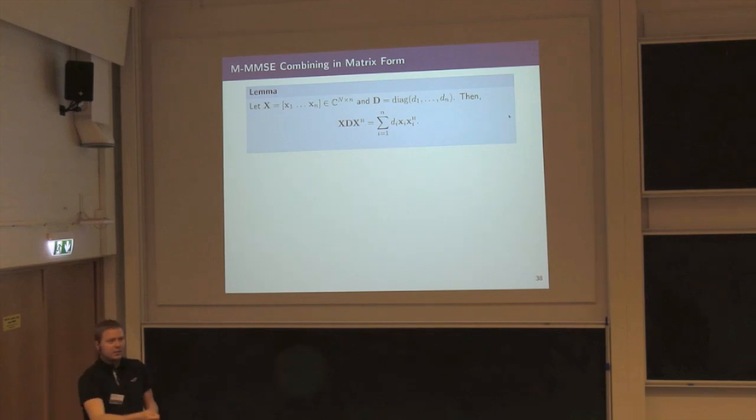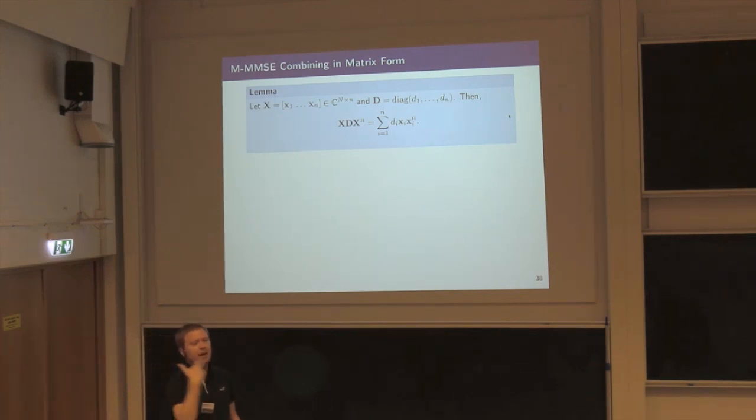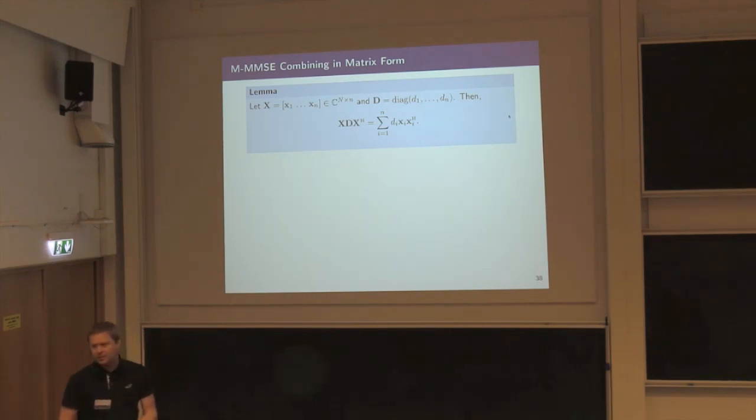So that is what the multicell MMSE is doing. It is whitening the received signal. It is then applying a maximum ratio combining filter, and then we have the MMSE, the best solution.